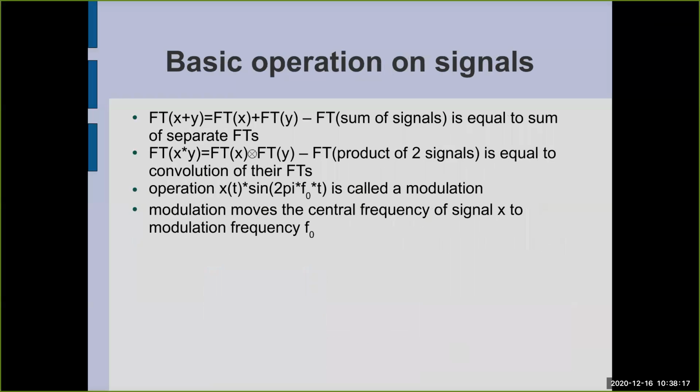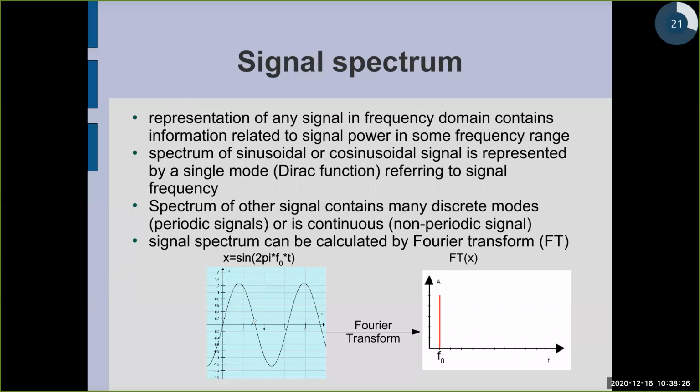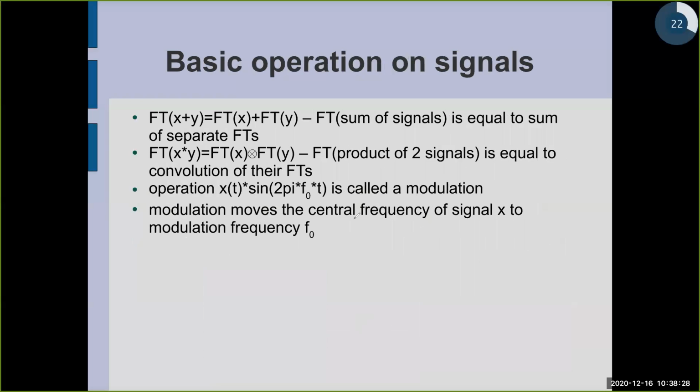And the second feature is that when we multiply two signals in the time domain, the resulting spectrum will be something which is called the convolution of their spectrums.